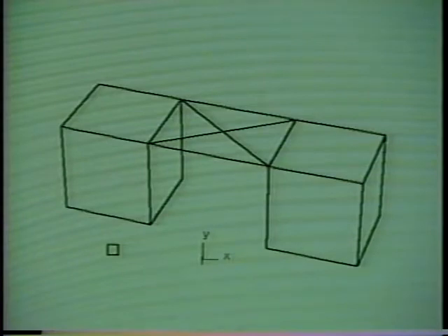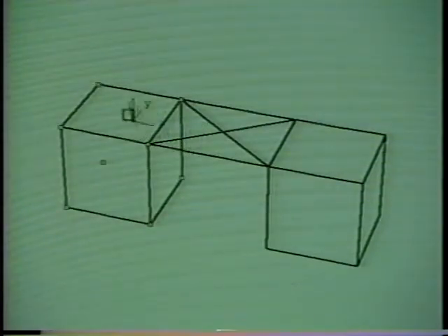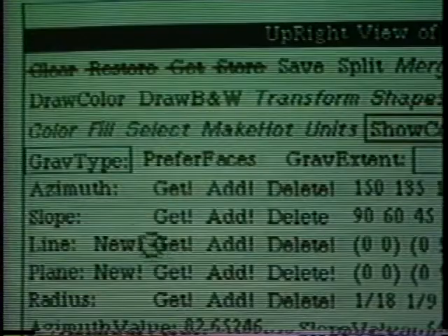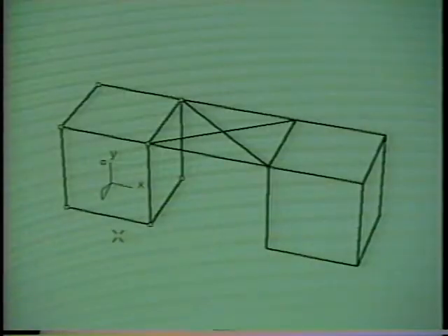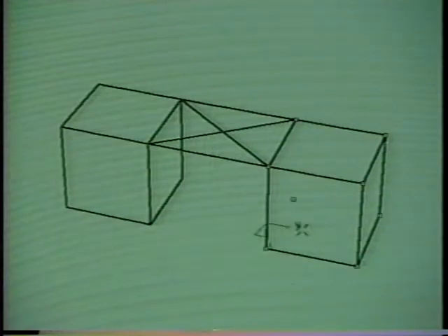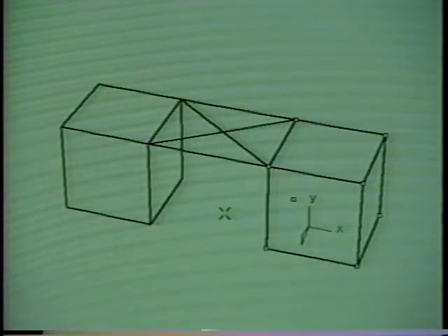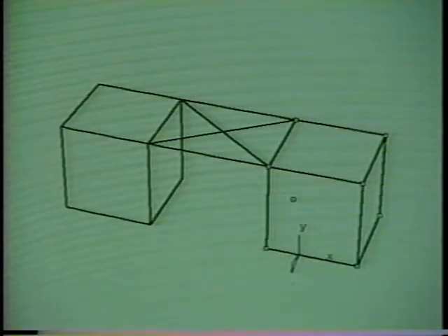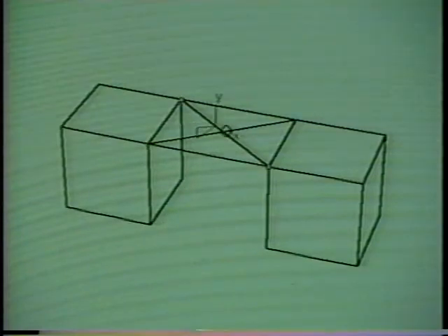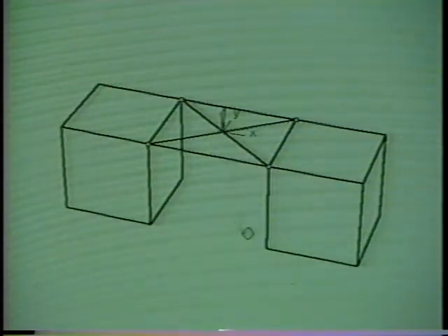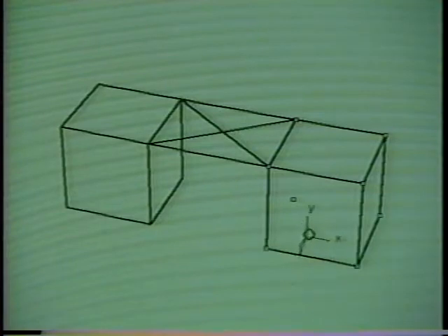Gargoyle 3D provides 3 gravity modes, which determine what part of an object the skitter will snap to. Face's preferred gravity snaps the skitter to the nearest surface. Line's preferred gravity snaps the skitter to the edge that appears nearest to the cursor, or to the nearest face if no edges are near. Both visible and hidden edges are gravity active. Finally, Point's preferred gravity snaps the skitter to the nearest vertex to the cursor, the nearest point of intersection to the cursor, or to the nearest edge or face if no such points are near.